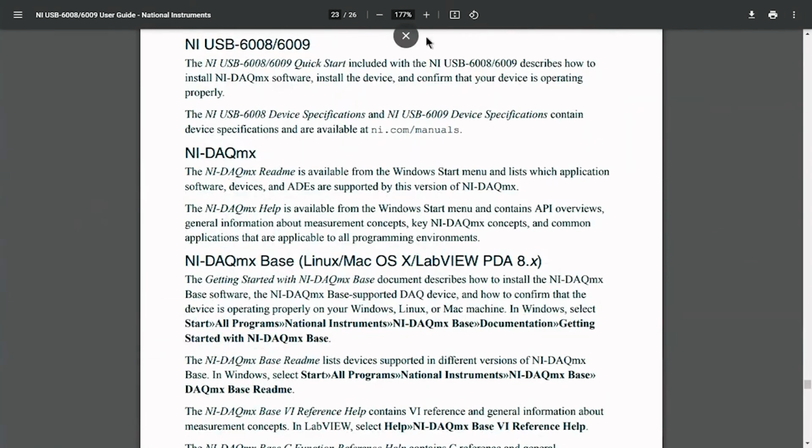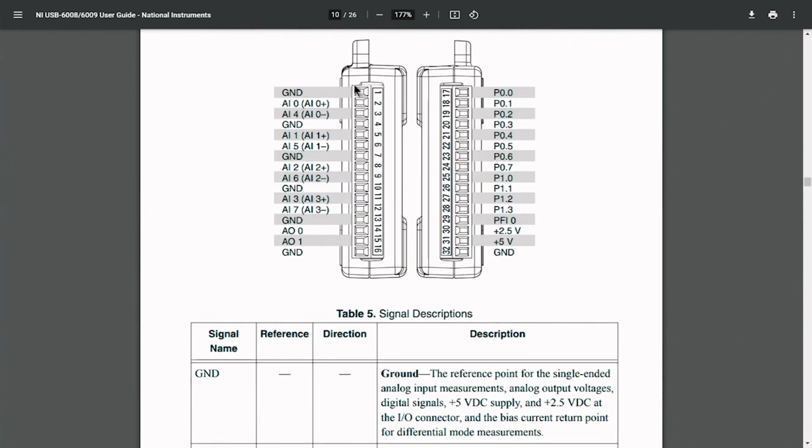Now we will see how we create a program in a lab environment in order to acquire the data using USB and the configuration connections between input and output. Here we can see I will use analog input 0 and the output will be connected to analog input 0, since the power required to power the LM35 temperature sensor can be utilized from the DAQ.